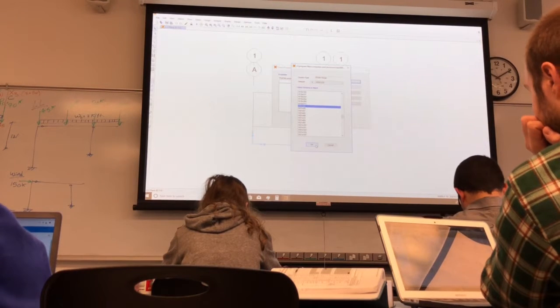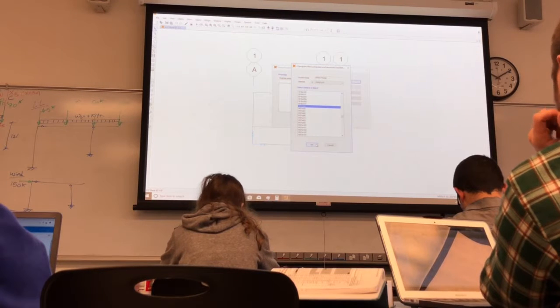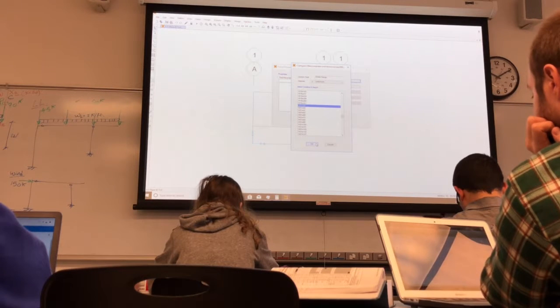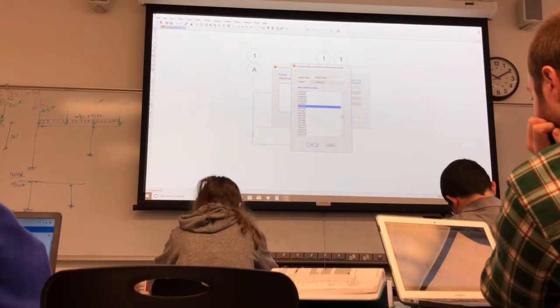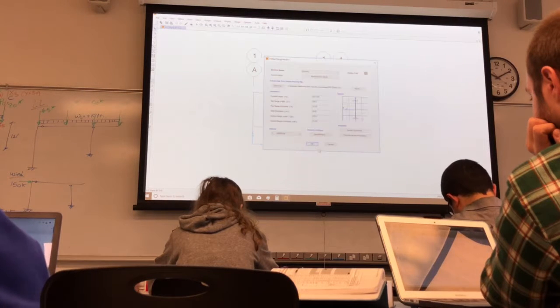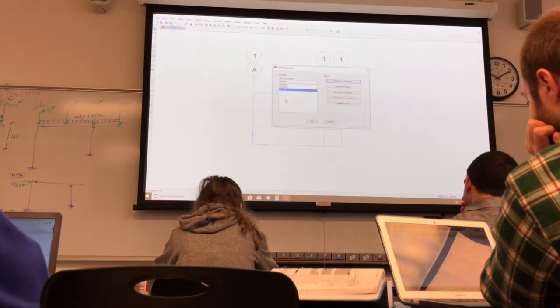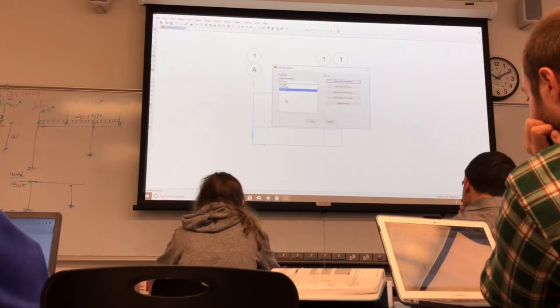So, yeah. When you clicked on AISC, which one did you click on? The first one, the AISC.PRO. Okay. Yeah, that's the first one. The other ones are more like seismic and code forms. They have more sections I don't need, so I go with the simple one. So I just click OK, and you'll see these sections now. These sections will show up here. So I have them. I just imported them. All I did was import them from AISC. Got them here. So any questions so far? It's straightforward, right?